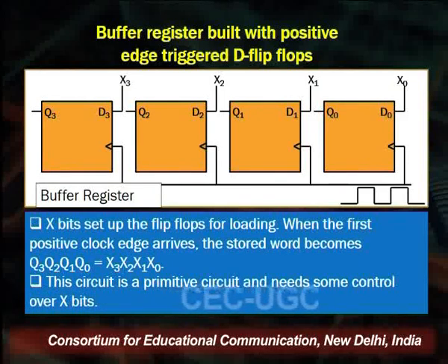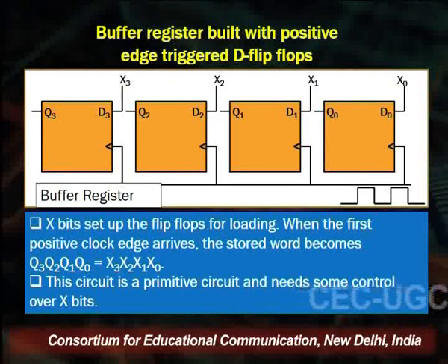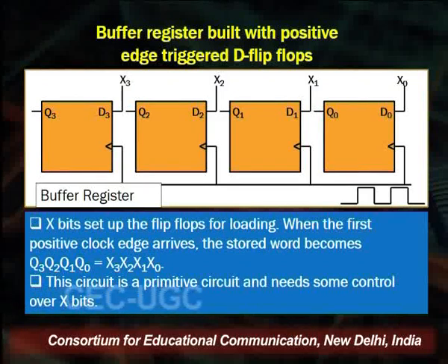Another important thing to summarize from here is the maximum amount of data we can store in this configuration. Any flip-flop will store only 1 bit. Therefore, having 4 flip-flops implies that the biggest data we can store here is 4 bits. There are 4 inputs here, hence there will be 2 to the power 4, that is 16 combinations.